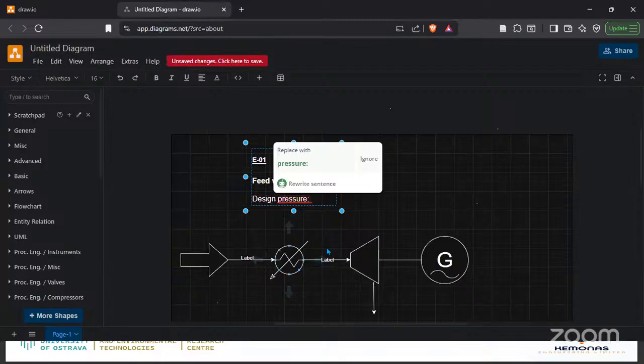So you go through the heat exchanger design, specify the maximum design pressure and maximum operating temperature according to the materials that will be used for the construction of the heat exchanger. All these are done during the concept stage when different stakeholders come together and make this decision.